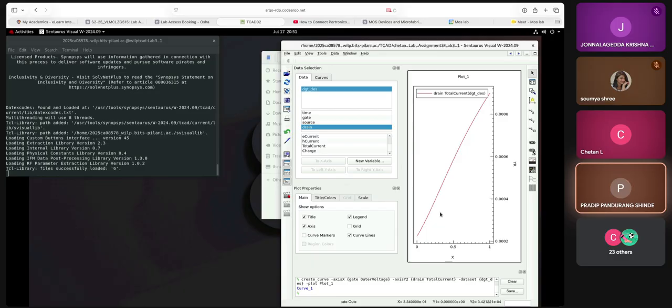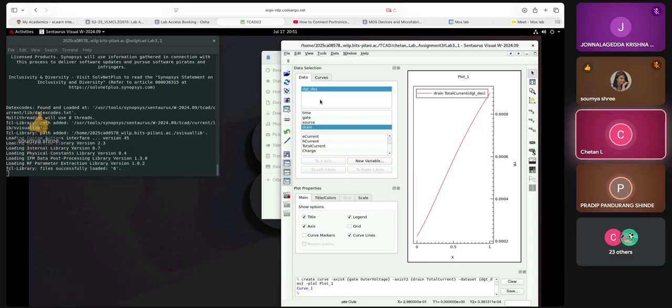Which file have you opened? Design.plt. This waveform shows our design is proper with the values that are expected. Considering this as a base, now we are going to the next step, plotting the three values from the assignment. This activity is to ensure that our MOSFET is giving proper ID versus VGS characteristics. If this waveform is not like this, then we have messed up in the .scm.